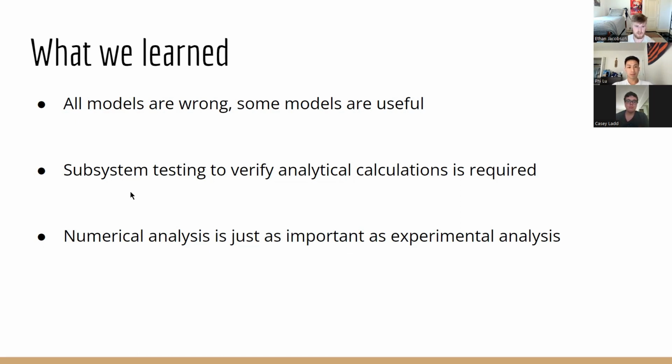Going on that, subsystem testing to verify our analytical models is also required. Examine the MOSFET and the LED driver. Those models relied on simplified abstractions of a diode and a MOSFET respectively, which are nonlinear devices. So using a linear model to approximate, we get convenient values and are able to calculate our resistors and capacitors that we need. However, as one of our challenges suggested, the models are wrong. We needed to have a bigger capacitor, and for the red LED, a much bigger resistor as well.